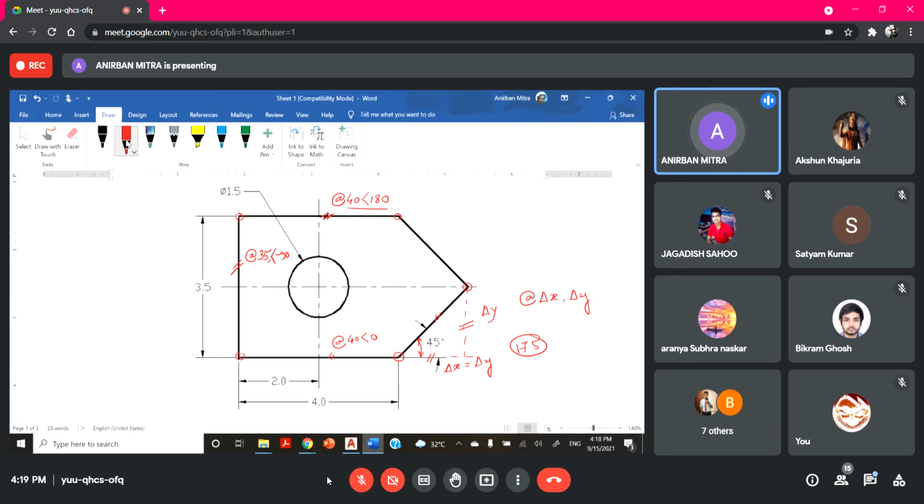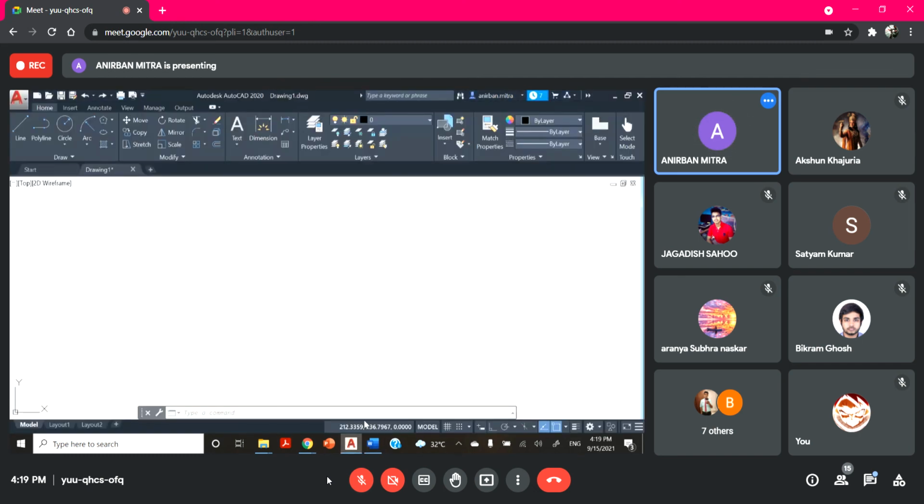So quite simply, I can write @17.5, 17.5, and I will get this line. Once I have got this, then it's pretty simple. I just need the O snap and the end option to be selected to close this thing off. So let's try it out here.